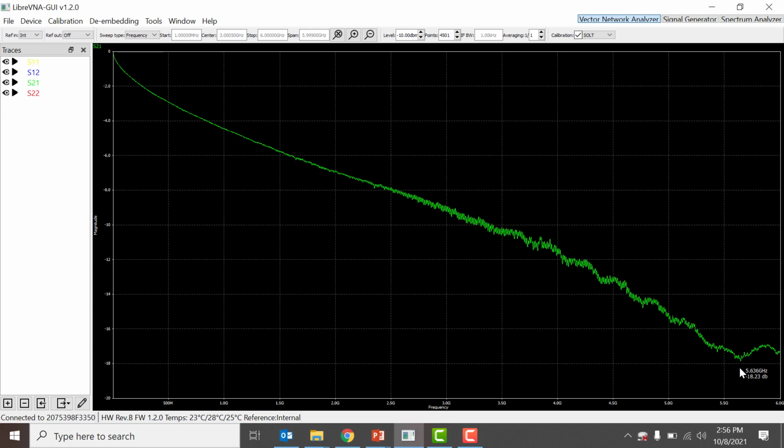And so everything we've talked about for transmission lines can't account for this effect. Our transmission line model was a bunch of daisy-chained LC sections. So there was some inductance per unit length and a capacitance per unit length, which we used to model our transmission line. But inductors and capacitors are lossless components, and so we can't explain this loss. If we were to measure the reflection coefficient, we would see that there would be very little power reflected back to port 1. So that's not an explanation. The power is being lost along the length of the transmission line.